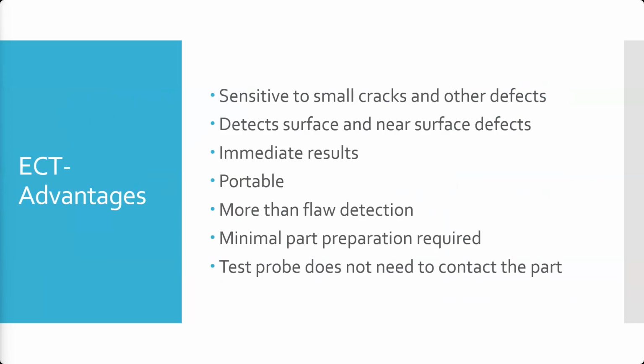Because when you're using this to test the skin for cracks around every single rivet on a lap splice, a lap splice that runs from the nose of the aircraft to the tail, and is 6 rivets wide, and there's a rivet every inch, you can think about how many rivets you have to do. You kind of go into a bit of a daze sitting there running a probe around each and every single rivet. Having something that gets your attention if it finds something would probably be helpful.